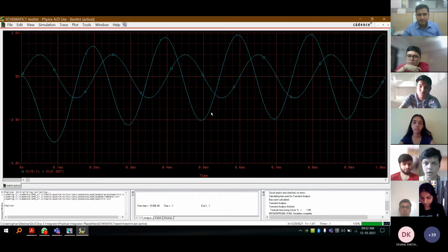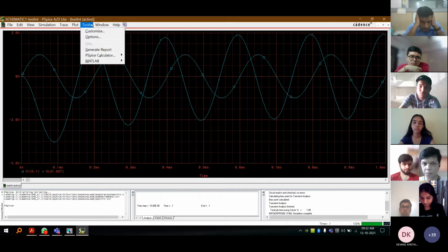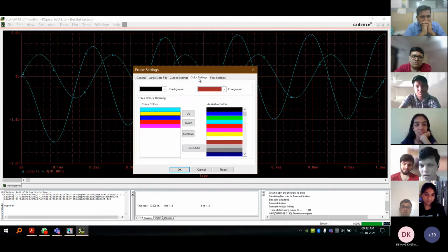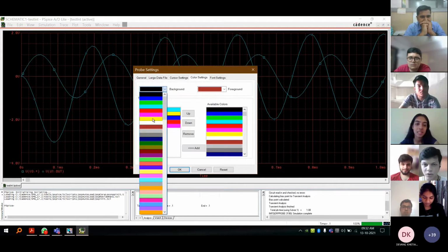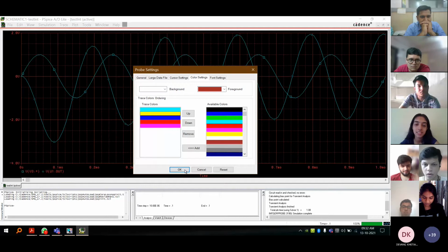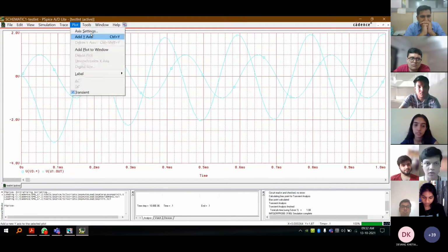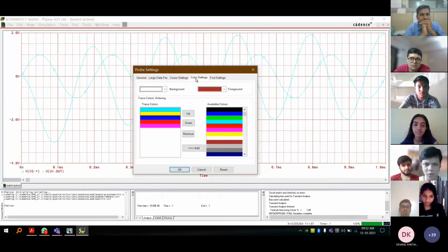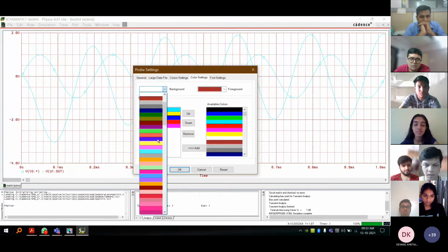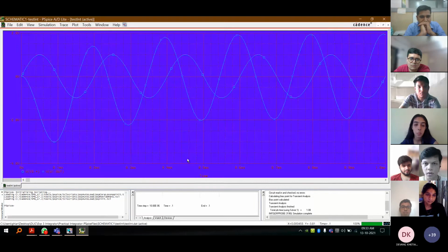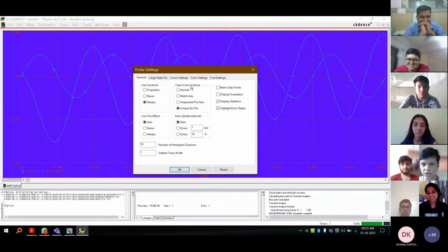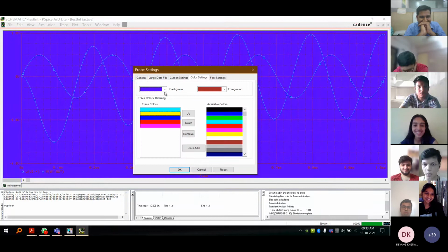Yes. So one thing that you can do to sort of spice up, no pun intended, your outputs is you can go into tools, the tools button up here, go into options and go into color settings. This is where you can change the background of your outputs. For example, I made it white. It's a bad decision because my colors are already, I am using, I think, a teal blue. So let's say I can make it blue. And there we go. It looks horrible, but this is a good way to change the output and input waveform colors as and when you need.